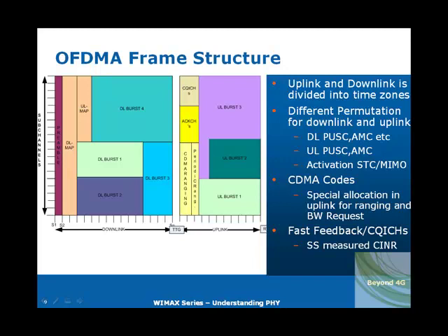We are on slide number 9, and in this particular slide the key structure of the OFDMA frame is presented. On the left side you can see that the first symbol of an OFDMA frame is a preamble, and then we have the downlink map and uplink map, and then users are allocated data bursts. Between downlink and uplink we have a TTG gap, which is called the transmit transition gap, and then we have an uplink burst, which is characterized by 3 symbols of control channels. One of them is CDMA ranging, then we have periodic ranging, then we have ACK/NACK channels, and then we have